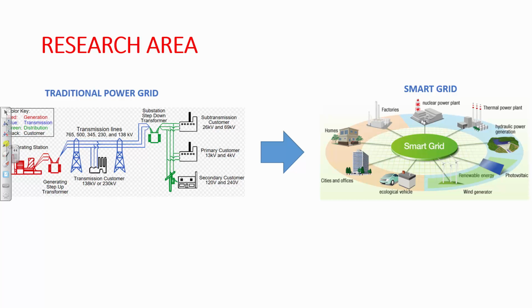If this campus was designed as something called a microgrid, that means we have our own generation installed on the campus, here in the distribution area. So if we lose the connection with the power grid, we can operate as an off-grid system. We can supply our local load from our local distributed generation. That will increase the resiliency and the reliability of the system. The smart grid will be a group of interconnected small microgrids. So if you lose one main generation, the system is designed to supply its own power from its own generation. That definitely will increase the resiliency and reliability of the overall system.